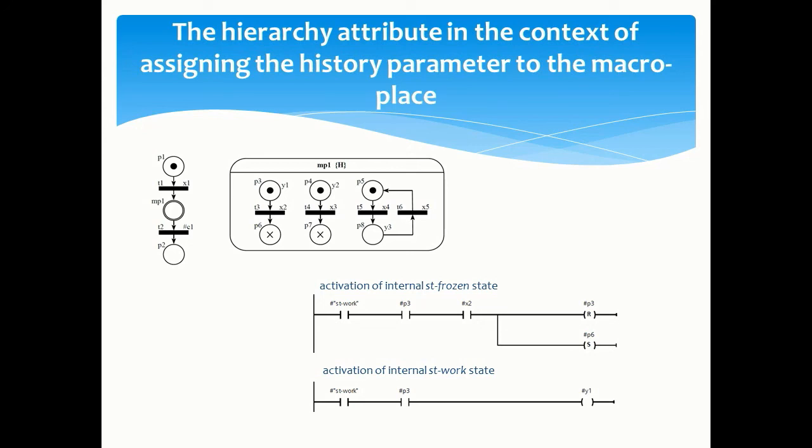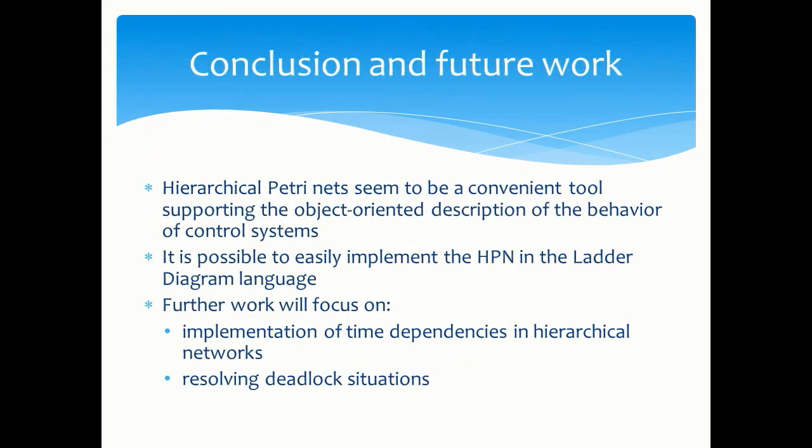Hierarchical Petri nets seem to be a convenient tool supporting the object-oriented description of the behavior of control systems. It is possible to easily implement the HPN in the ladder diagram language. Further work will focus on implementation of time dependencies in hierarchical networks, and resolving deadlock situations. Thank you for your attention.